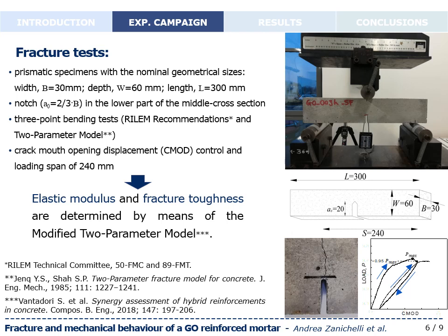So the elastic modulus and the fracture toughness have been computed as a function of the experimental values of both the peak load and the initial and unloading linear elastic compliances.